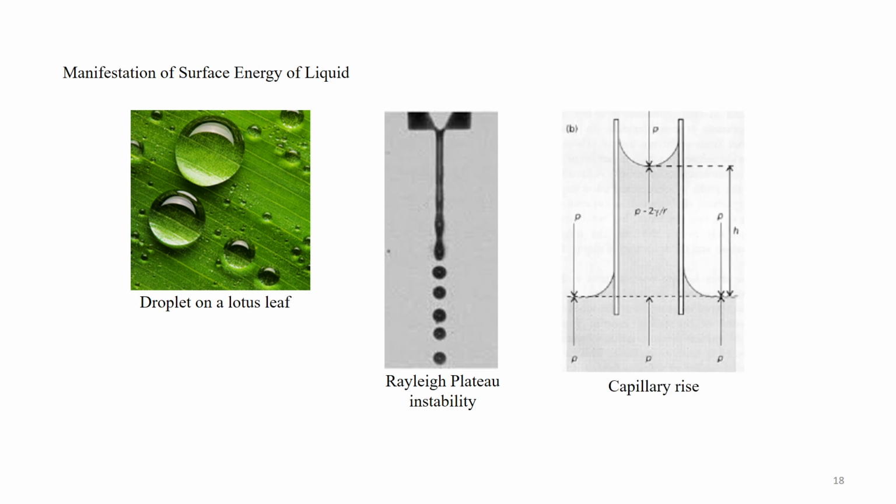Here also is capillary rise. You take a thin hydrophilic capillary and put it inside a pool of water, and you will see that the liquid rises to some height. Why does it do that? This is called the capillary rise, and it is also driven by surface tension of the liquid-air or liquid-vacuum interface. That drives this effect.